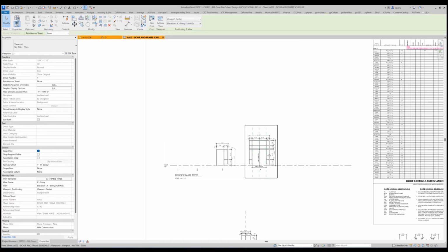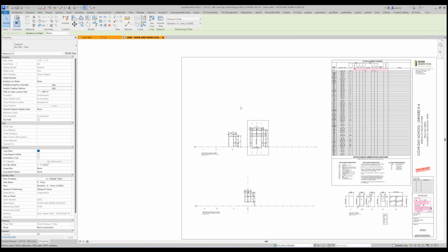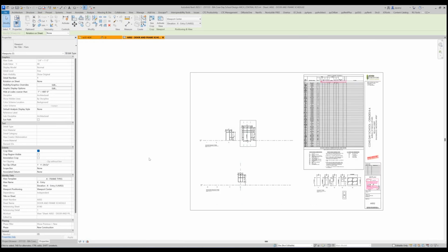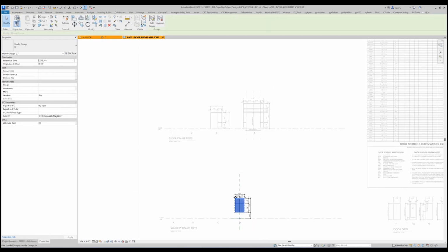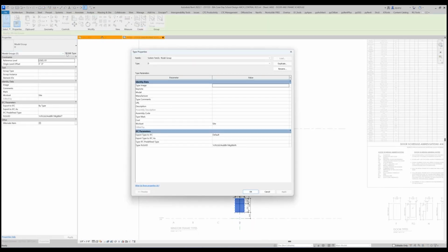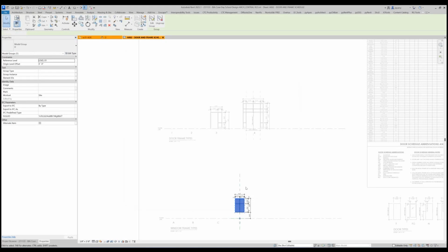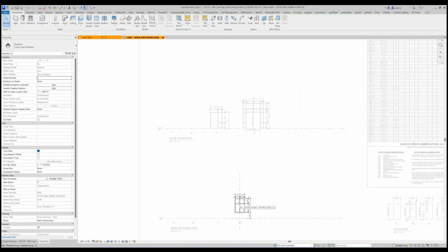I can have another one called X dash standard small or whatever kind of verbiage you want to use. That way, when you go back later to renumber and rename, you can get them right here and then get them right on your plan when you tag them. It's easier if I've created this group, I could do a type mark for the group and we could tag those. But I didn't want to confuse people. They just made that available a few versions ago.